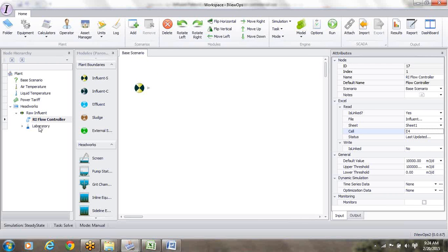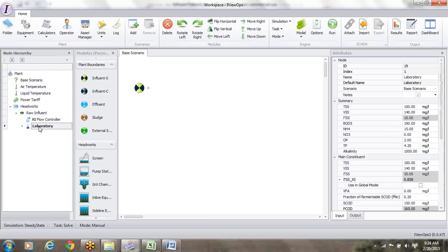Okay, the lab section. The lab section is of course very important, and what we are putting in here in the simple influent is, if you're going to set up this plant to get the correct mixed liquor, in this case you would put in the equivalent of the last 15 days average of strength. In a more sophisticated plant model, there are better ways to handle that, where we use a baseline flow and an actual flow, and we look back at the last 1 year of data for the baseline. But here, let's say the influent is 250.